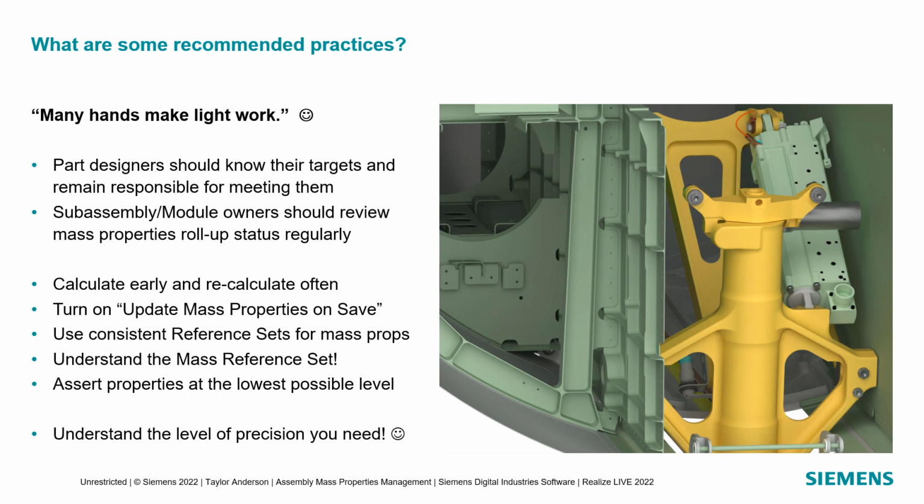I recommend that you automate everything you can here. There are a bunch of things we give you there. I encourage you to check out the customer default options carefully and to set those site-wide as needed. That's very, very useful to look at, and we're happy to talk with you about some best practices specifically there. One of these is the model reference set or the mass reference set. This is the model reference set by default. NX likes the model reference set by default if you can stick to it.